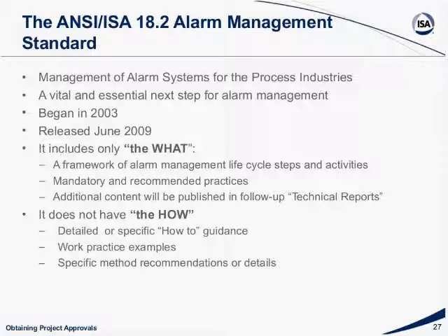The what is very prescriptive in the ISA 18.2 document, and it talks about the alarm management life cycle, the things you have to do. It has mandatory and recommended practices and other technical reports that follow up.